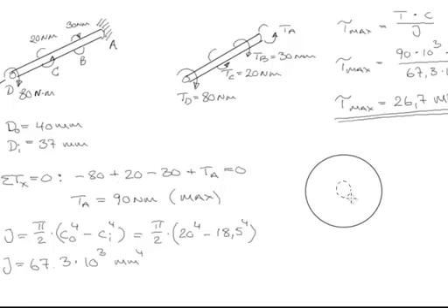If we just take a look at the tubular section, then I can try to calculate or show you in a diagram here. If this is then our y-axis, and this is our z-axis, then the shear stress follows a curve that's linear if we are within the linear elastic area.